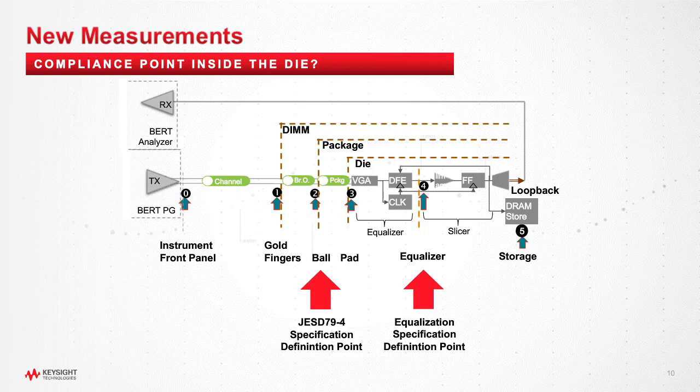And this is the same kind of challenge that next generation DRAM finds. There are some signals where the traditional specification point at the ball of the package will continue to work. But there are places, once the eye closes, where that will not work anymore. And it's quite possible that the spec will have to be written again in a very different way.